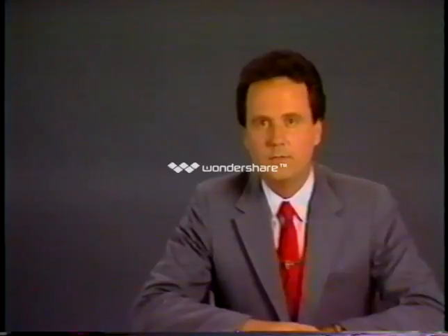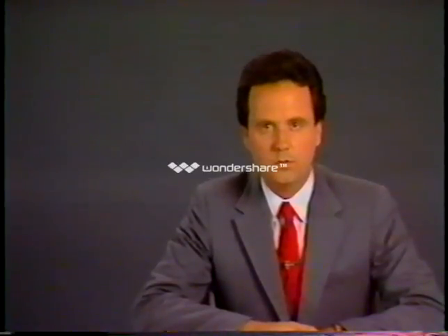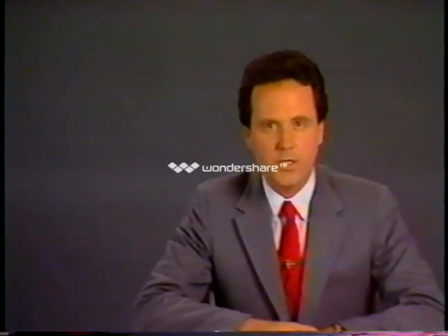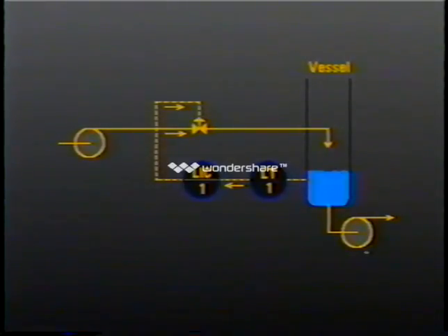Our second example concerns level control. As shown in the illustration, the vessel is drained at a constant rate by this pump. Since the primary objective is to maintain a steady tank level, the main load therefore becomes the inlet flow rate. Since the inlet flow represents a fast developing disturbance to the tank level, there may be significant deviations from the tank level set point as a result of inlet flow changes.